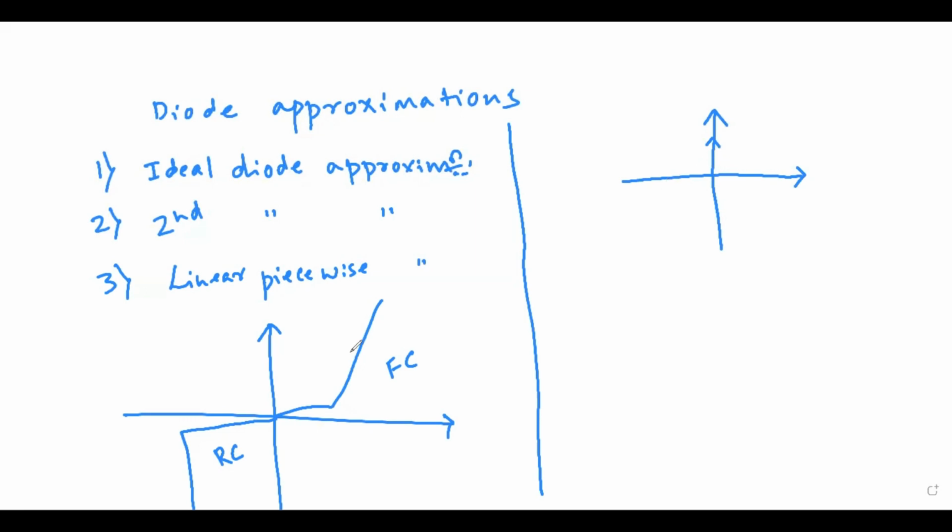In the normal diode, when we consider this VI characteristics, we can see that up to this particular level, called the threshold level, because of the depletion region, there is no flow of current, or a very minimal flow of current. But after this threshold, once the depletion region completely vanishes, the current increases linearly. It is not increasing suddenly, and this linear increase in the current is due to the forward resistance.